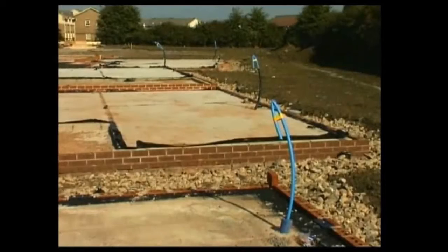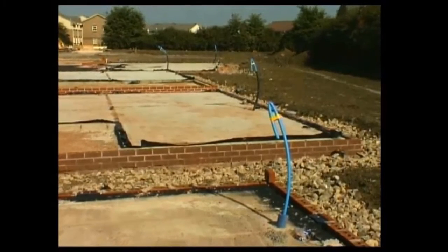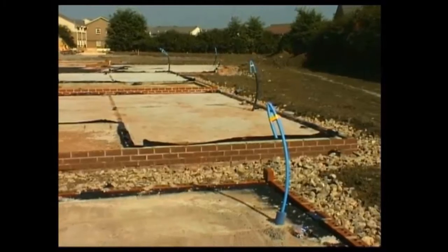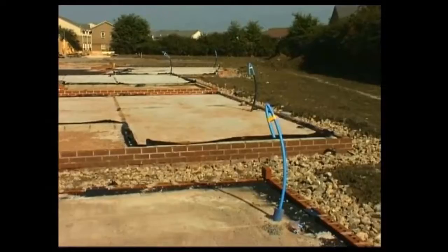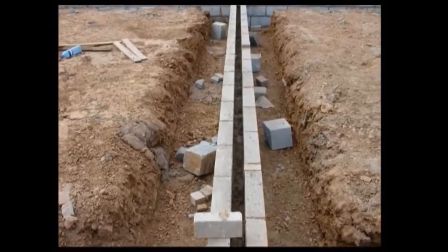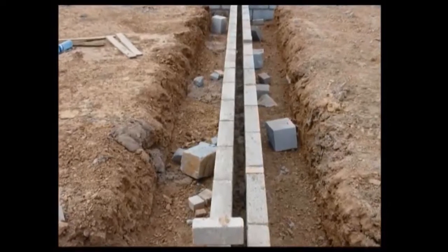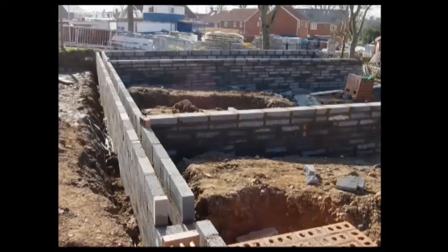In some situations, the use of a ground-bearing concrete slab is not suitable. These include some clay subsoils, high water tables, and deep hardcore. If the hardcore is less than 600 millimetres deep, it's fairly easy to compact and the risk of future settlement is slight. However, where the depth is more than 600 millimetres, or where the slope of the ground results in hardcore of uneven depth, there's always a long-term risk of settlement.